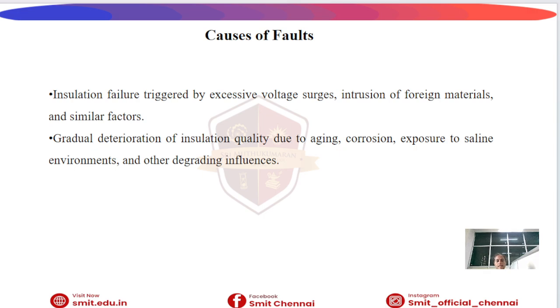And causes of faults. Insulation failure triggered by excessive voltage, such as intrusion of foreign materials and other factors. Gradual deterioration of insulation quality due to aging, corrosion, exposure to saline environments, and other degrading influences.